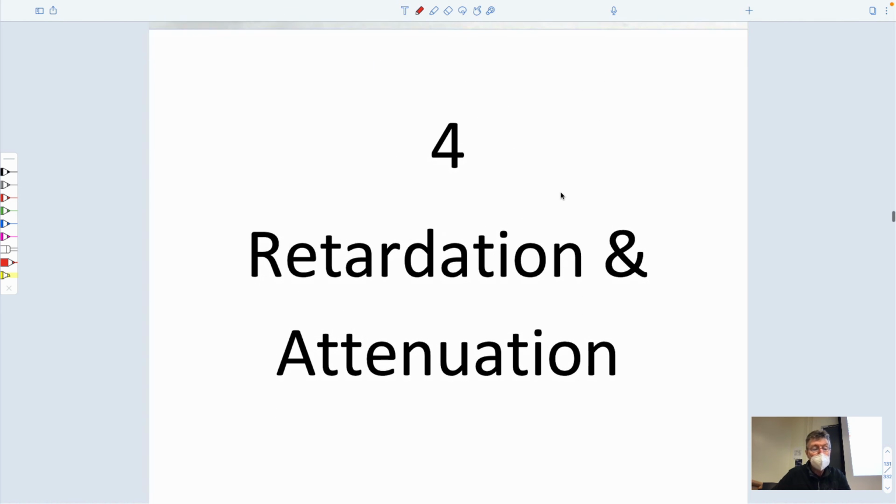So what we've talked about so far has been what we'll call conservative transport. And conservative transport means that the mass of solute that's in water is conserved within the water and isn't removed onto the porous medium it flows past. It turns out that DNAPLs, once they dissolve in water, are actually quite reactive with the porous media they go through, and therefore they are attenuated by being attached to the porous media, and the rate at which they go down gradient is retarded, slowed, versus a conservative plume. And so the next thing we'll talk about is transport for real materials that have that kind of behavior attached to them. Okay, that's it.